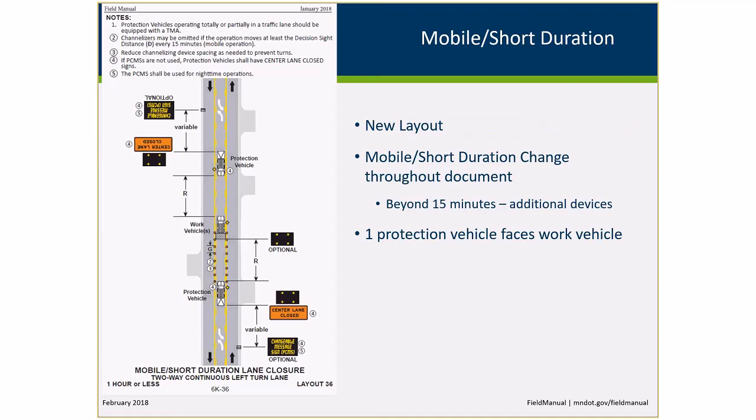And there's a reason why we chose 15 for that, and why we separate mobile and short duration. Short duration is a longer time frame. Workers are more exposed. Drivers need more guidance in order to get around that area. So there's a difference between these two. What we ended up deciding is actually combining them into the same layout, but if you're going to go beyond 15 minutes, you need to provide additional devices.